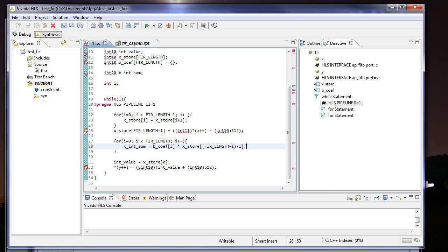So there we go, it's that simple. And the final thing we also have to do is get our fixed point back. So we've multiplied 10 by 10. Remember, 1 bit is used for the sign. So actually what I'll do now is shift left 9, and this will get me back to the point.